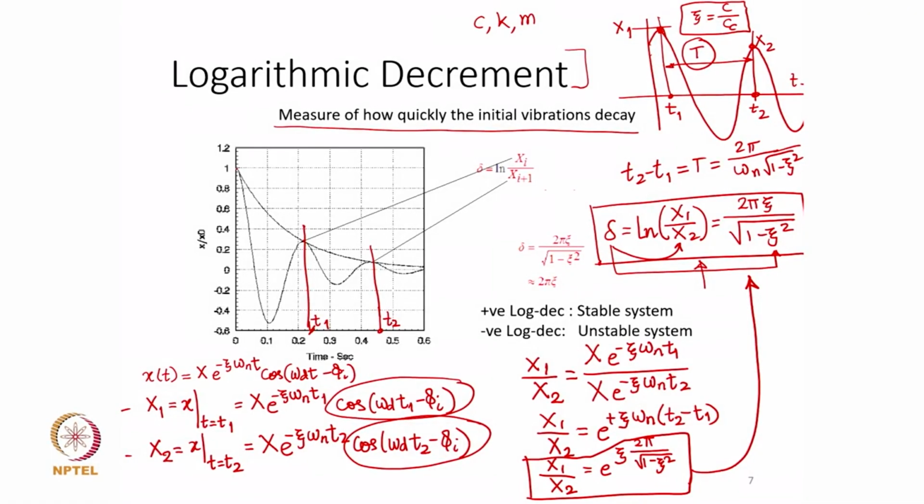So, if I can capture this vibratory response, measure it, the sensor will give me a measured vibration response like this, and then from this measured data I can find what this x1 is, I can find what this x2 is. So, from the measured values I can get to know the damping, the level of damping in the system, without worrying about how much mass the system has, how much stiffness the system has. Okay. So, knowledge of the system parameters is not essential here.